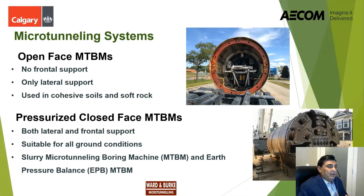So now once we know the ground condition, we have to select a microtunneling system. There are basically 2 microtunneling systems: open face microtunneling boring machines and pressurized closed face microtunneling boring machines. Open face machines don't provide frontal support, as they are open from the front. They provide only lateral support, and they are good in dry soils, cohesive soils, and soft rock. Pressurized closed face MTBMs provide both lateral and frontal support. They are suitable for all ground conditions. And there are 2 types of pressurized closed face: a slurry type microtunneling boring machine and an earth pressure balance microtunneling boring machine.